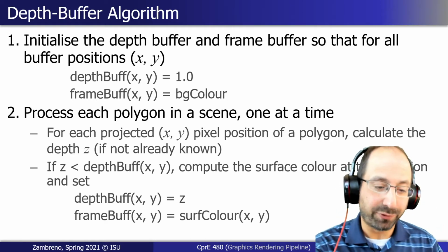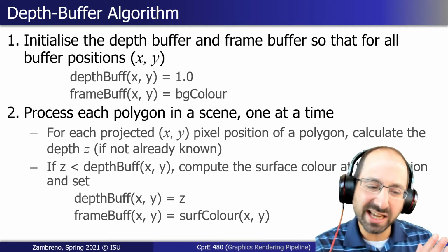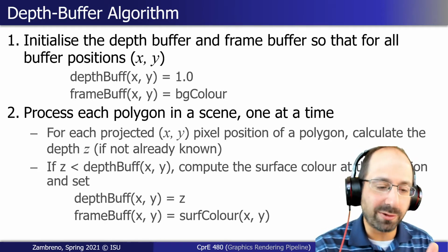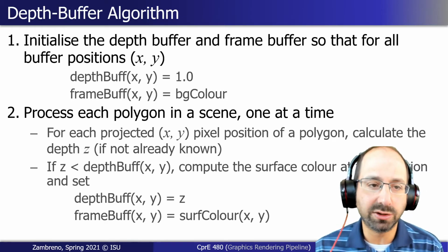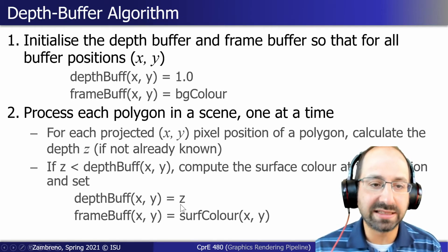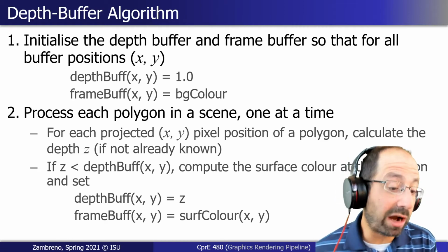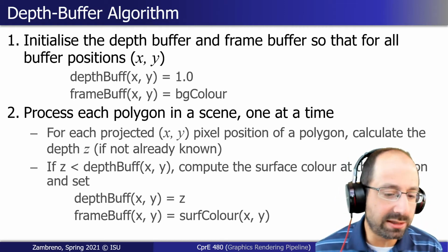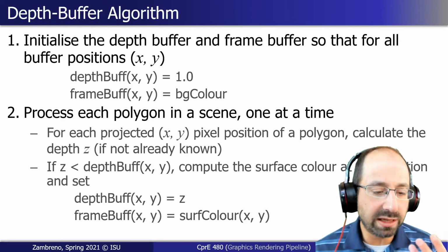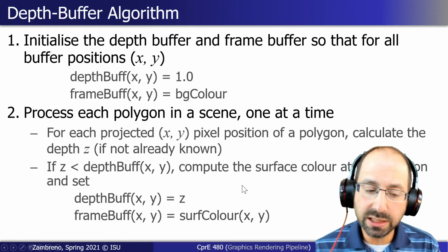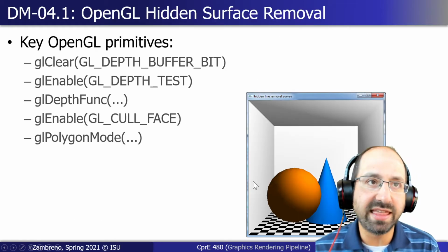And we write to both buffers then, because we'd want to update this XY location with this color, this shade of red, green, blue, and also have this depth information updated and associated with it. That's the two writes that are happening here. So the state machine isn't really that much harder in render output to support this, but it does have to be updated to be aware of that. And that's what will give you your image-based depth buffer implementation. There's really no more to it than that.